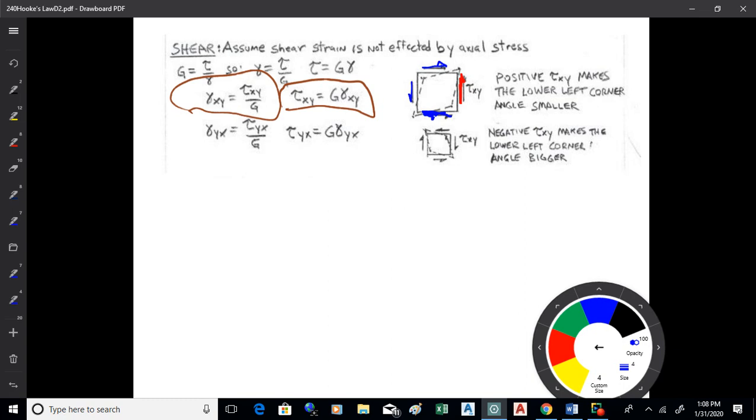All right. Now, if you have that stress pattern, what that's going to do, if you think of these stresses as being vectors, which actually, they're not really, but they kind of act that way, the net pull would be upright and down left. So those 2 opposite corners would pull out. The other 2 corners would come in, to be pushed in.